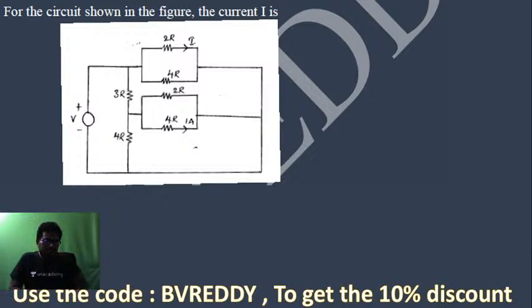Now tell me this problem. Find I. They ask to find I here. This current, here this current is 1. So how much is this voltage? Yes, 4R. Now this voltage is also 4R only. Yes or no? That means this current is 1 ampere. This is also 4R. That means this current, how much is it? 2 amperes.